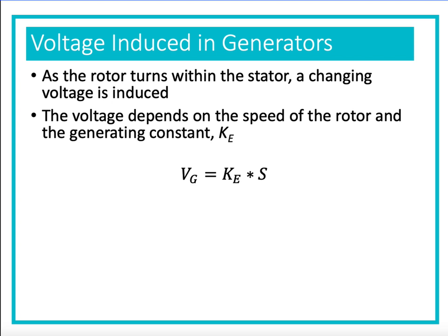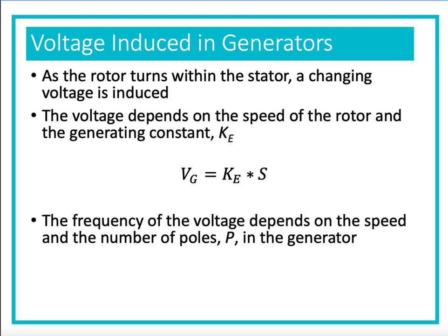Anytime you have a coil, you have some kind of magnetic field, you're going to have a north and a south pole. If the rotor has only one north and one south, that is a two-pole system. If it has sets of windings such that you actually have more than two, since poles are always in pairs, you could have, say, four, where you had two norths and two souths. That would be a four-pole generator.